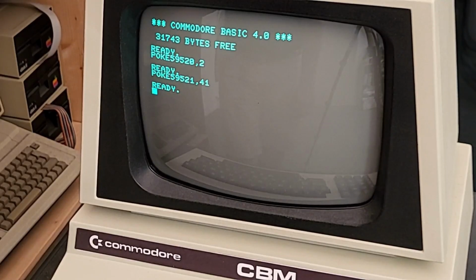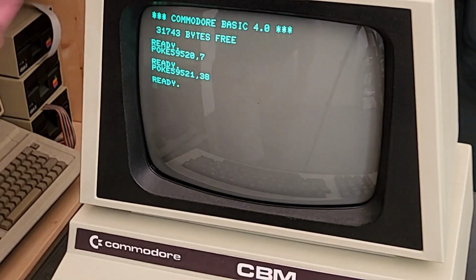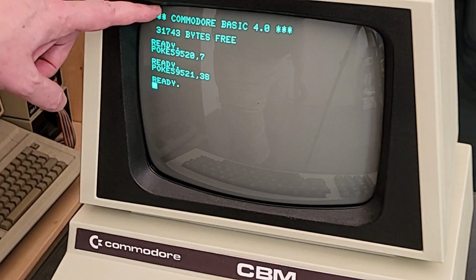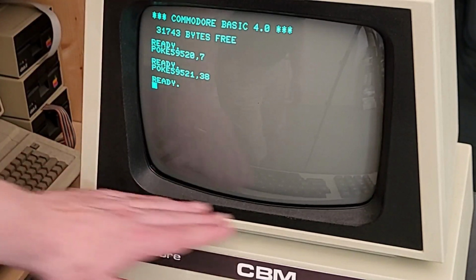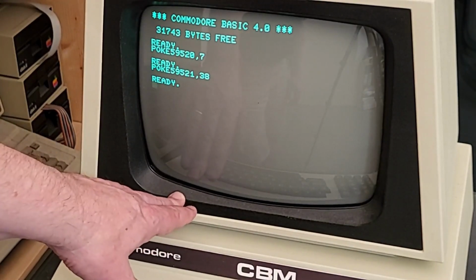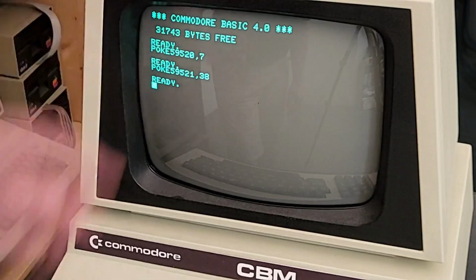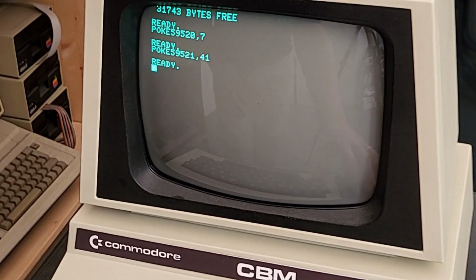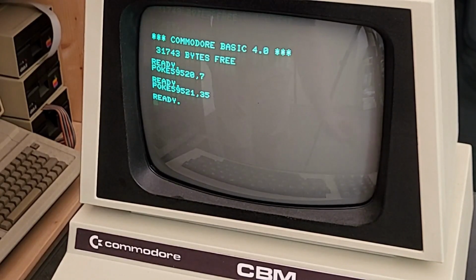So let's look at the vertical sync, which is register 7. When we go here and put in the default, which is 37, nothing happens. But we can also increase it, like I showed on the slide, and again the screen moved up because I've increased the distance between the start of screen and the vertical sync. The vertical sync is basically tacked to this bottom of the screen, so the whole screen, the start of screen, moves up. And you can also go down. Oh, sorry, the other direction.